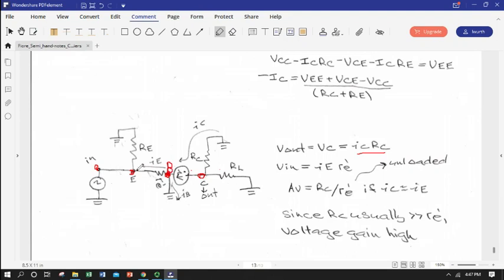So there's a R little e between the emitter and the base. This is just horizontal configuration of the same AC model. We know that the emitter current flows between the base and the emitter through the BJT over our R little e. Well, the base is grounded, so the base is at 0 volts, effectively defined as ground. So the emitter point is 0 minus emitter current times R little e. So effectively, these are both negative numbers, and that's why we don't invert. Current is flowing from ground and going down in both cases.